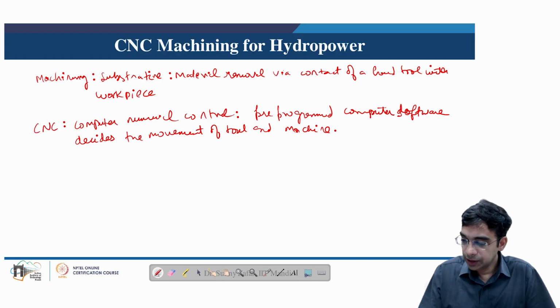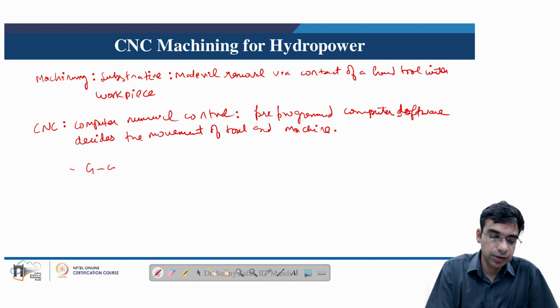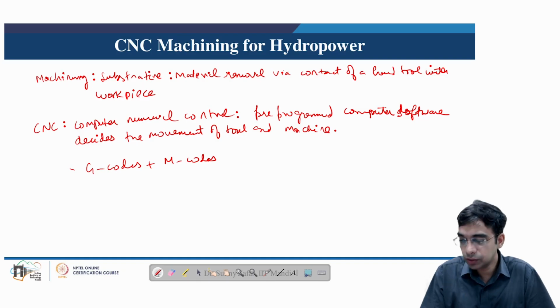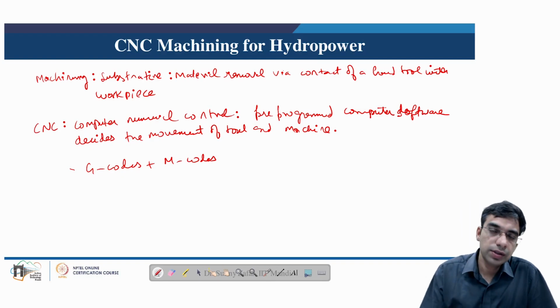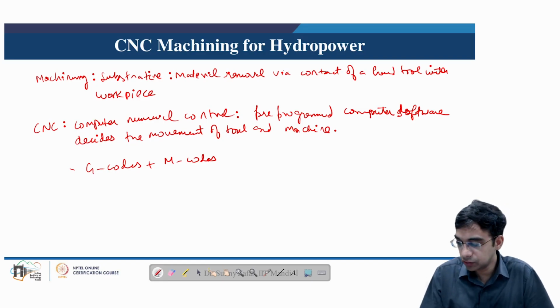So in CNC machining, the numerical control software is pre-designated with the use of G codes and M codes. So these G codes and combination of M codes comprise the basis of the CNC code, which is basically a language to control the behavior of the machine tool, which includes speed, feed, depth of cut, changing tool, turning off or turning on the lubricant, and so on.